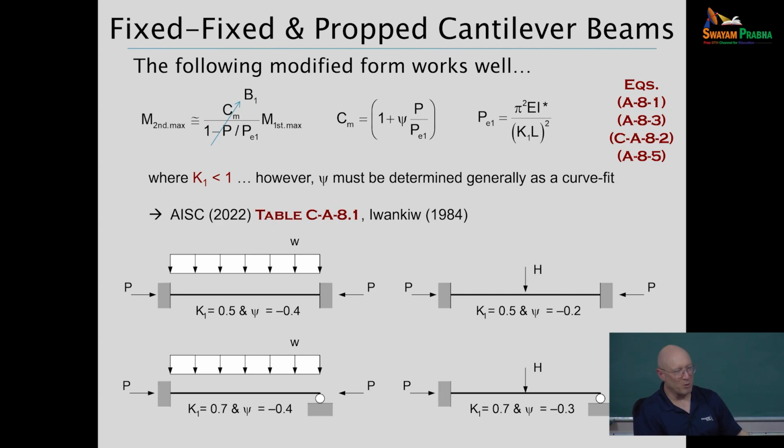The Eurocode is based more on an Ayrton-Perry approximation. We'll talk about what that is and how that works. I'll compare and contrast a bit, but I didn't want to come here and lecture you about how we do something in America that is nothing like what you do here in terms of the stiffness reduction. I'll give a few reasons why we think it's a good way to go in the Americas, and then leave it there. So the EI star is where, at least in the Americas, we implement a reduction on the bending rigidity as part of our elastic analysis calculations.